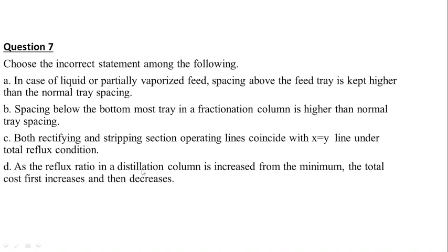As the reflux ratio in a distillation column is increased from minimum, the total cost first increases and then decreases. The option D is an incorrect statement. On increasing the reflux ratio in a distillation column, the total cost first decreases and then it will increase again gradually.